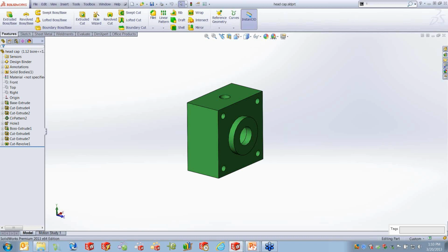What about turning your threaded components into dummy solids? Will this help the rebuild time? It's not really going to help. It may help a little bit, but it's really the number of faces created by the threads that adds more time to the calculation. You're going to remove the time it takes to rebuild the feature, but it still may take just about as much time to calculate the graphics for a complex thread with all those surfaces. So I would create a simplified part and have one with threads and one without, and do it that way instead.